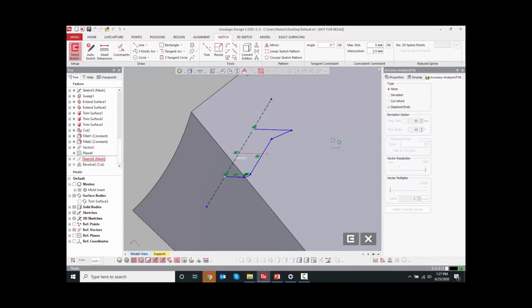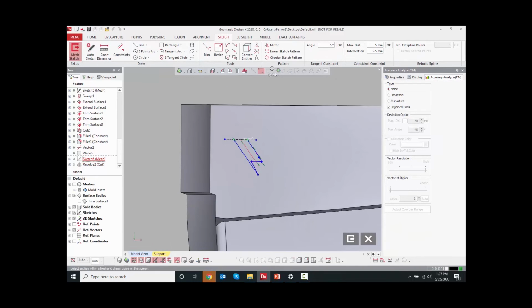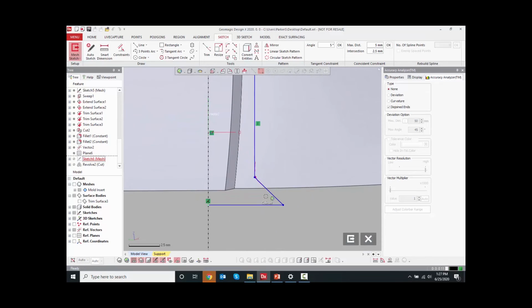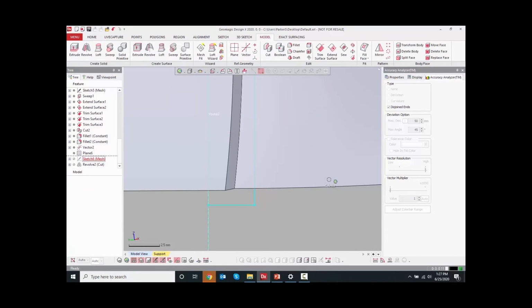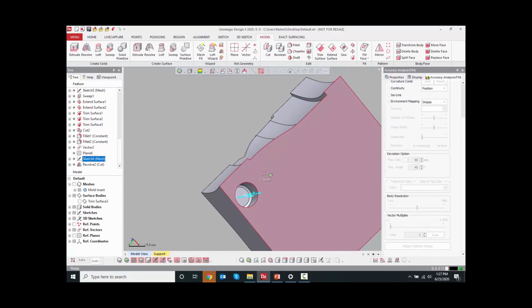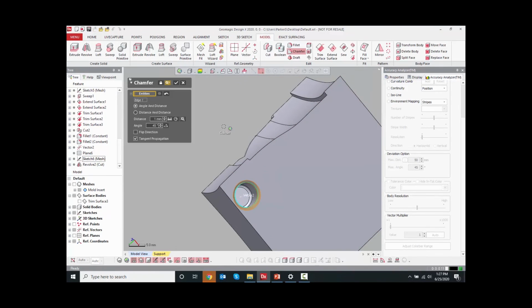But I can do that really easily here. This is a sketch that the software created. I'll just remove that angled feature there. Finish this sketch. It's just a basic cylinder, and it still does a cut operation, and now I can use my chamfer tool. The chamfer tool has the same searching function for the dimensions of that chamfer. So if I want to edit this and make it 0.4 and 45 degrees, I certainly have override capability there. But that basically does it.